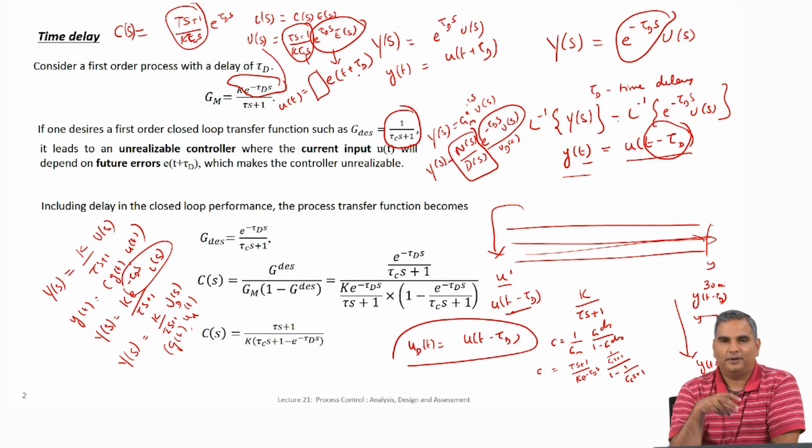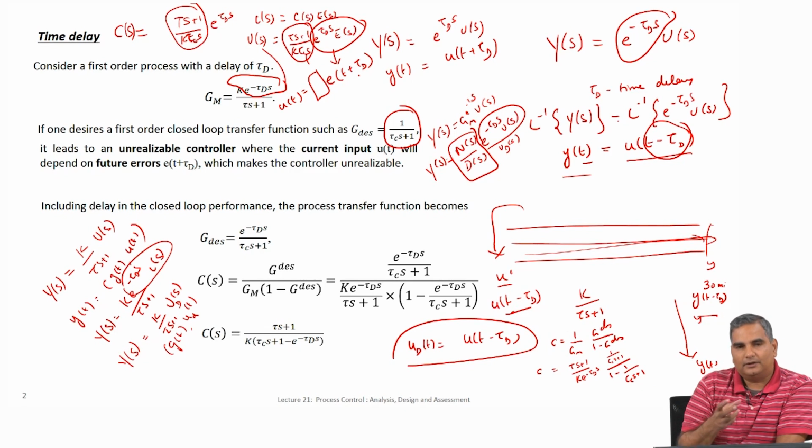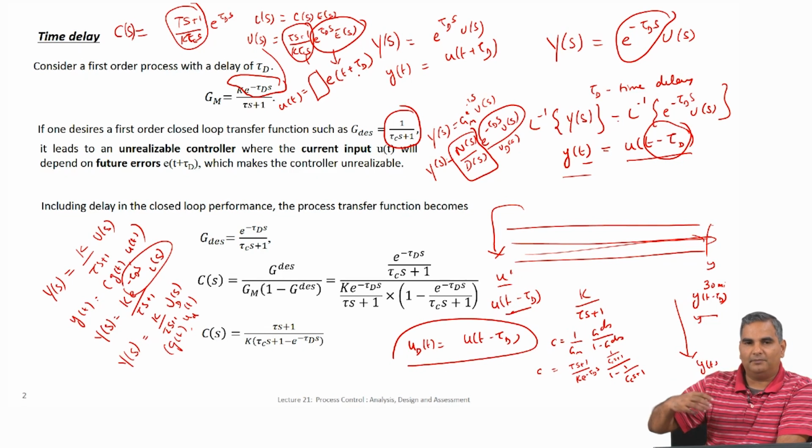This is because when you have these systems and you have pipes where water is there, because the external atmosphere is pretty cold, you have cold water in the pipes, and it takes a while for this water to drain out and the hot water to come from its source into the bathtub, right. So basically what it means is there is a transport delay. Though you have opened your hot water knob, this action is not going to immediately result in hot water coming, right. So all the water in the pipe has to drain out before the hot water comes,